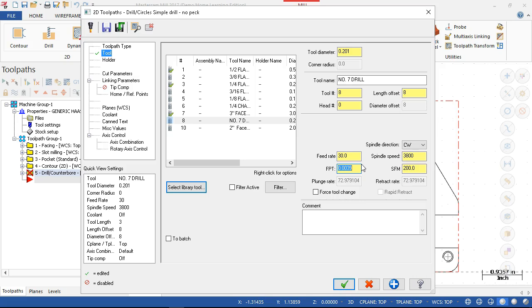I understand. But if you went right now, you changed the feed rate of the speed. If you went back over to the surface feet per minute and changed that to 150, it's going to change the feed rate, isn't it? Yeah. Yeah. Because it's going to update the calculation. But going slower also means that my inch per minute or my feed per tooth calculation changes the feed rate.